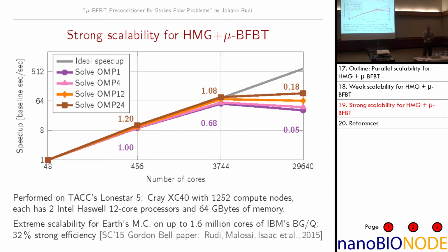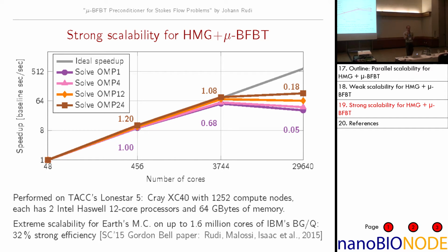So I would guess that AMG is very good at this linear discretization, but as you go to high order, you get in trouble because it just cannot as effectively reduce the residual as you go through the V cycle. So it depends on viscosity and on the discretization. So you're saying it depends on what basis functions you want. Yeah, and I want high order, so it would be worse.